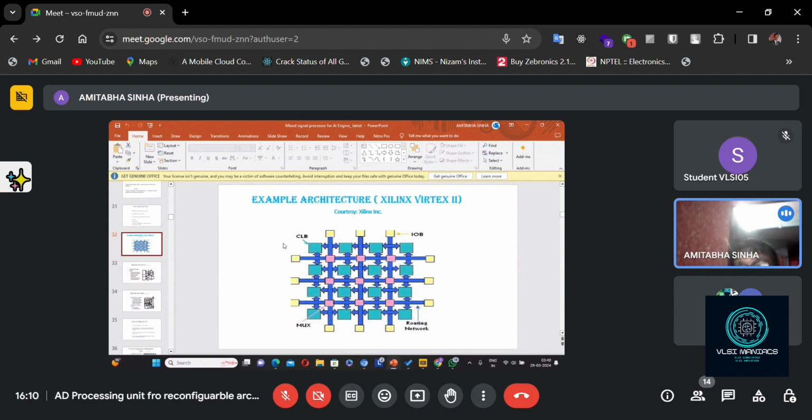So first, our selection should be based on what is the cost, what is the flexibility, what is the power dissipation, what is the robustness. From that point of view, FPGA offers very high speed, but of course that speed is less than ASIC. Why? Obvious question. The answer is ASIC doesn't require any switching circuits because ASIC has been designed for particular applications. There is no flexibility, but FPGA has been designed keeping a wide range of high-end applications in view. So to provide that support, we require these switches.